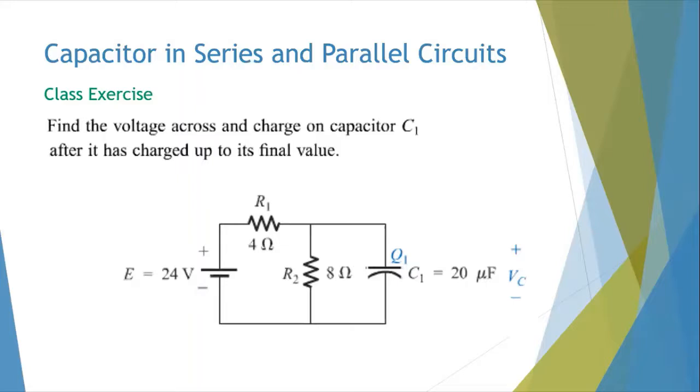The stage where it is stabilized is called a steady state, and the stage where things are still changing to reach that state of equilibrium is called a transient. So transient is a stage where things are still changing. As you connect a capacitor in a circuit, it starts to charge up to the final value, but the stage where the voltage is changing is called transient.